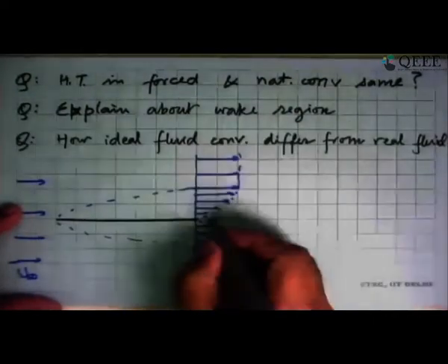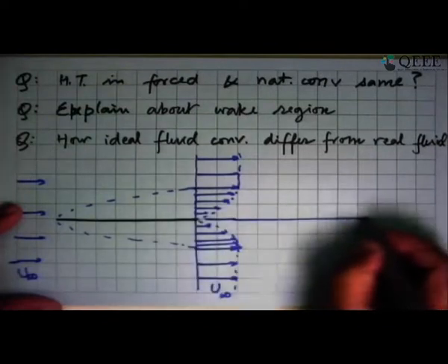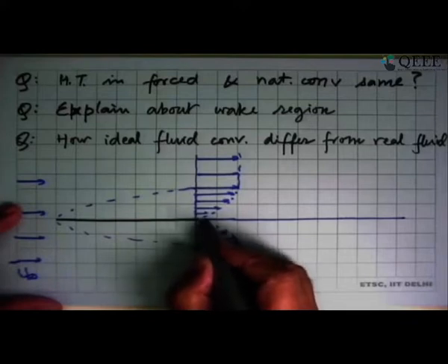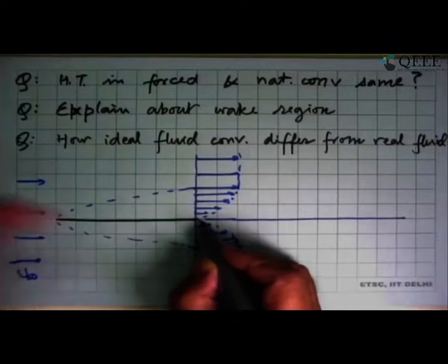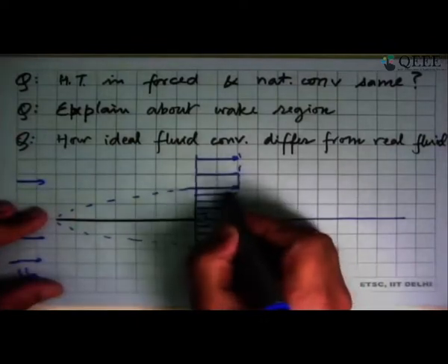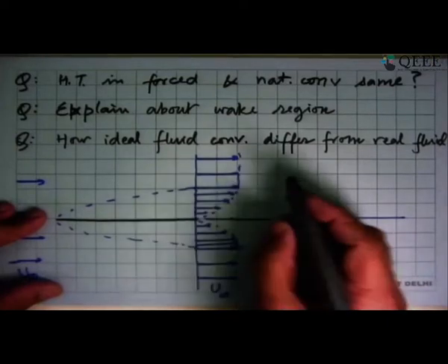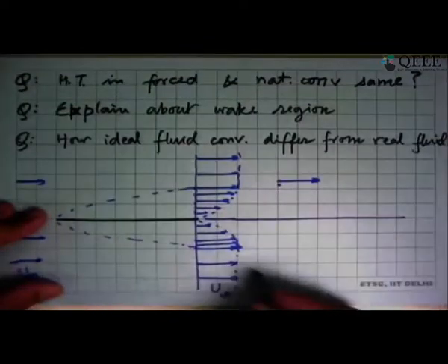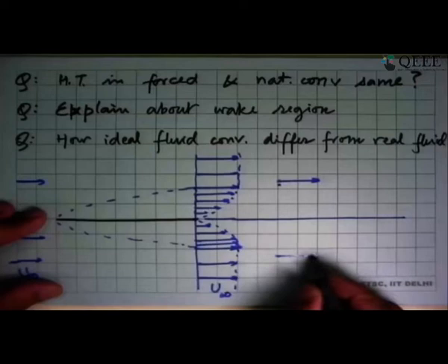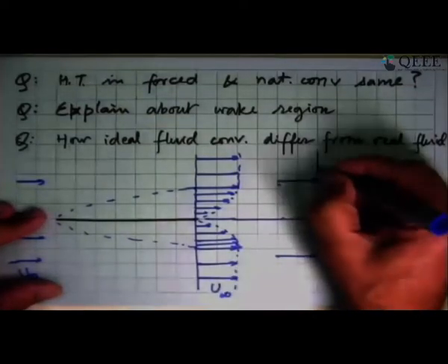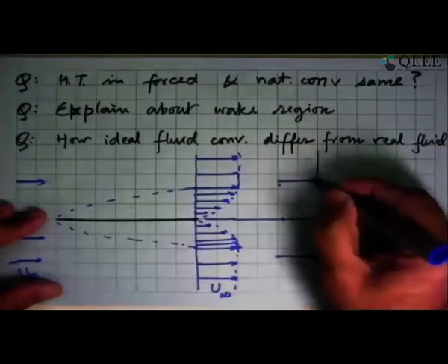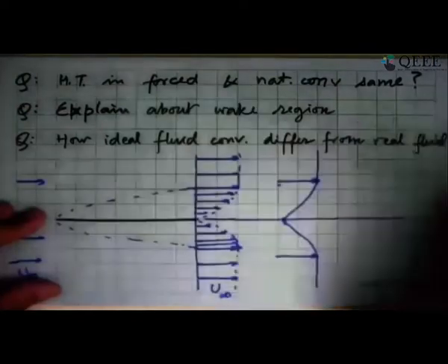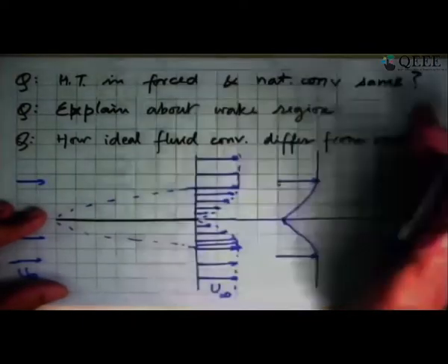Now what happens to this velocity profile is what we would see as you go back here. The point which was at zero velocity will take a finite velocity because the other fluid layers are moving around it. The deceleration that was felt up to this point will be felt a little beyond this point. So at this location, u infinity will come to this point. Similarly here, and the center line velocity will have increased. So now you have a velocity which is uniform outside this, and inside it you get a velocity profile like this. This continues for a very long time until finally it becomes straight.